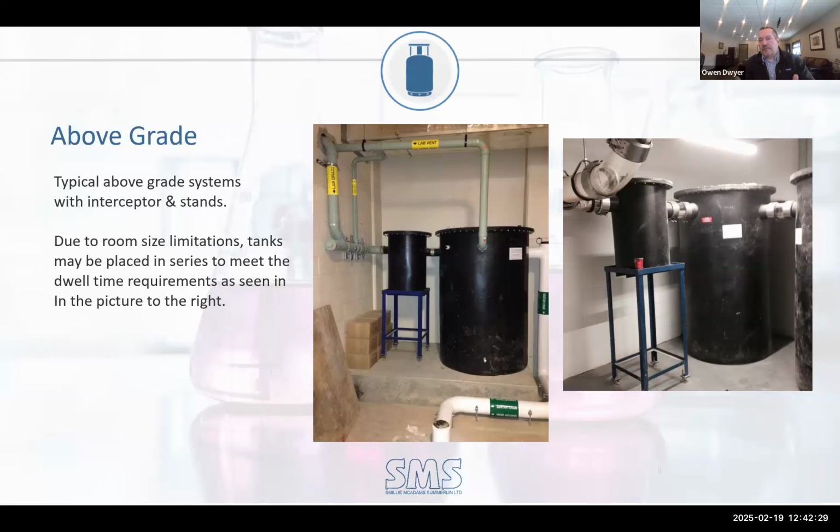If, for example, a 48 by 84 tank is too big to fit through the existing building, you don't want to start blowing doors open. So maybe I make a tank, or I specify a tank in multiple series that are able to fit through the hallways and into these facilities, into the doors.